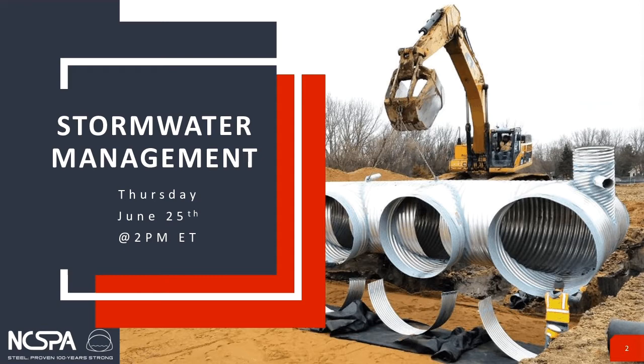An efficient and cost-effective stormwater management program may entail a variety of design elements depending on the site conditions, land use, and local regulations. Many of the components used in stormwater management systems can be manufactured using corrugated steel pipe, CSP. Stormwater management techniques can include structural design elements such as detention, retention, flow control, inlet protection, routing considerations, and water quality devices. Using CSP structures for design elements is an effective technique for achieving stormwater quantity and quality control.